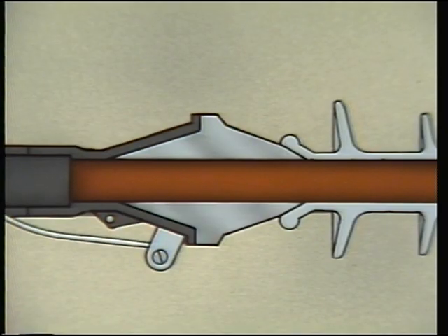The slip-on termination has a molded rubber stress cone. The cone works similarly to the stress cone that was built for the tape termination. Attached to the stress cone is a metal grounding strap, to which the concentric wires are attached for grounding the termination.